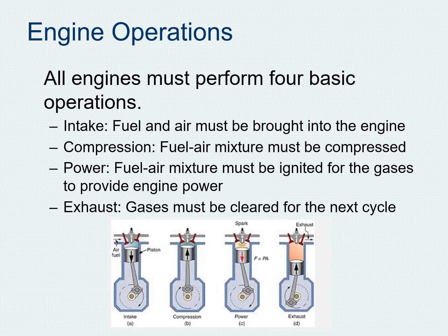Next one, engine operation. That means operation of the reciprocating engine. The four basic operations are: the first one is the intake stroke. Here the piston moves down, the inlet valve opens, the exhaust valve is closed, and the fuel air mixture comes into the engine. Second one, compression. The piston moves up, both the valves are closed, and the fuel air mixture is compressed.